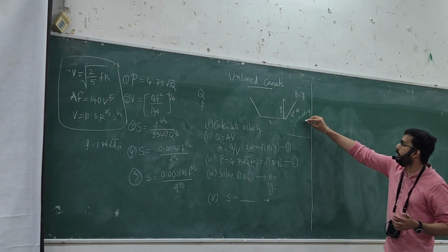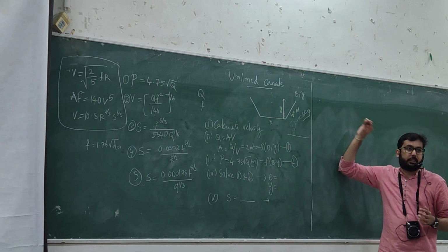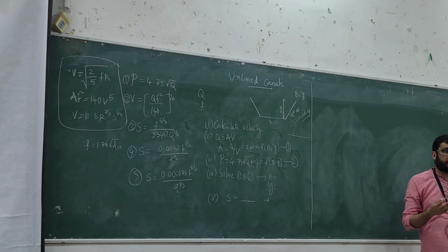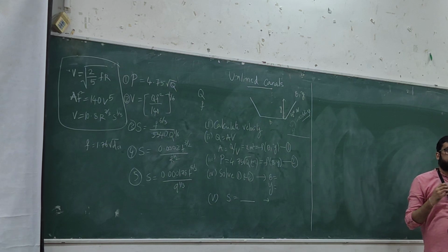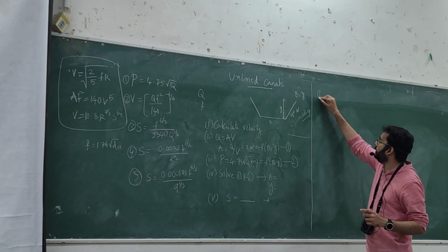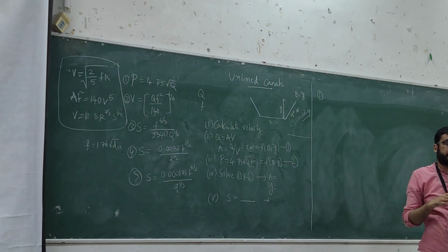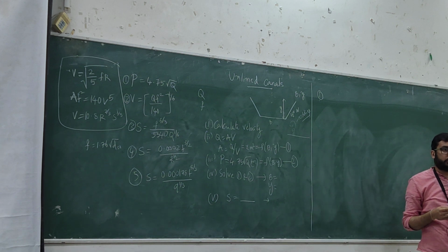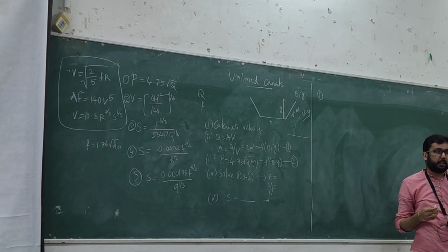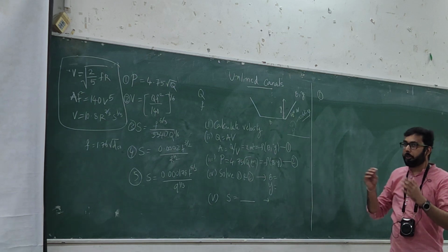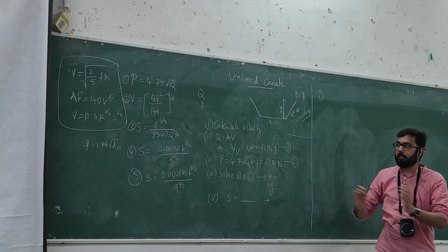Now, why are these eddies important in both the theories? So they are considering eddies as some main phenomenon, and why is it? So what is the objective that we are trying to achieve by designing through Lacey and Kennedy? So there are two conditions that we want to satisfy. One is no erosion, and whatever sediment has entered into the channel has to remain in suspension. So now put into context of the sediments and this turbulence.